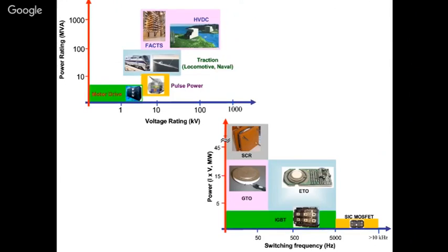So here, some of the applications are again shown. You have the FACTS devices, HVDC. The voltage rating, current rating, and the power rating are also given here, and similarly the devices which are used. For power around 45 kilowatt and megawatt and above, you can see SCRs are used. So for our application, what we are discussing in this course, mostly it is SCR based.